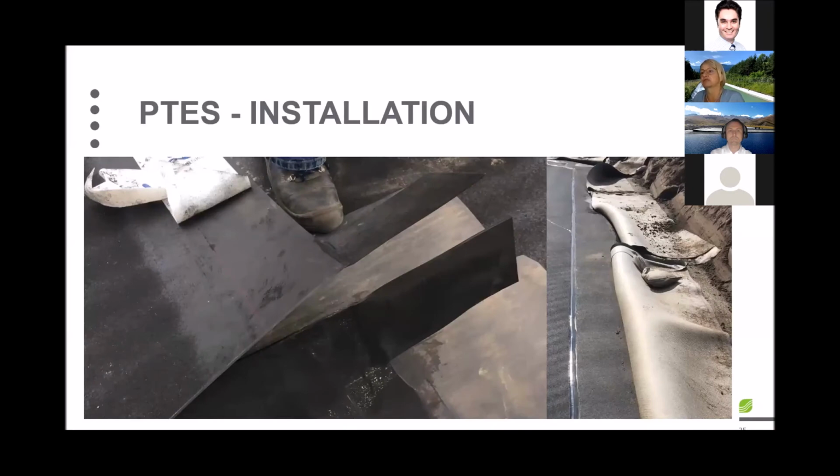Thus, I would like to show this picture, which shows how welds could be executed. The left side picture shows that there is a flap installed at the length of the geomembrane, which is helping to get the weld device into the weld zone. While the thickness reduction of the seam cannot be controlled in the flap, it's already a controlled thickness reduction when the weld device is entering this cross-sectional seam here, and thus a good seam quality can be achieved.